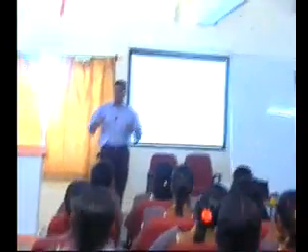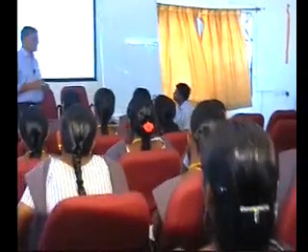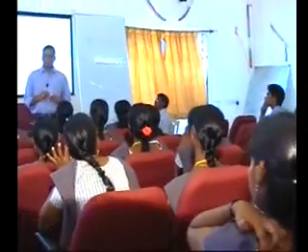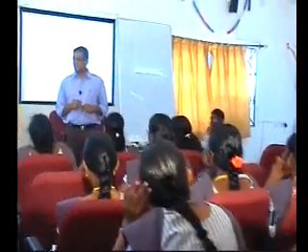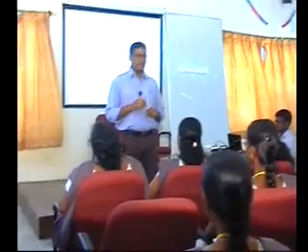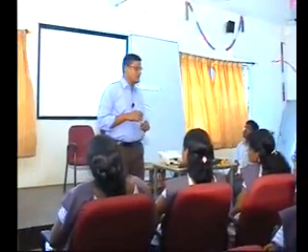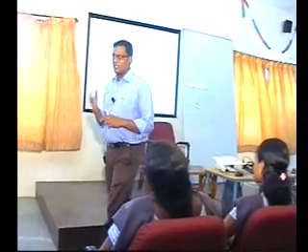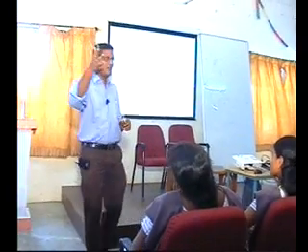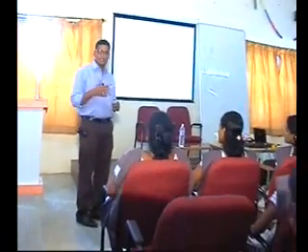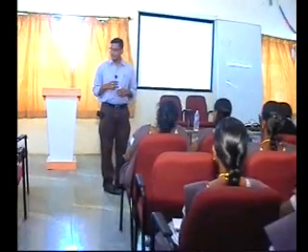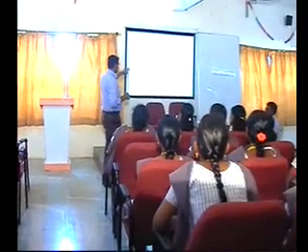What is the limitation of OrCAD PSpice? The textbook says that it has a limitation of around 68 nodes. OrCAD PSpice generally works on KCL, Kirchhoff's current law. People say it is 68, but we have seen up to 140 nodes also. We have simulated even more than 140 nodes using PSpice. So node limitation is one such.